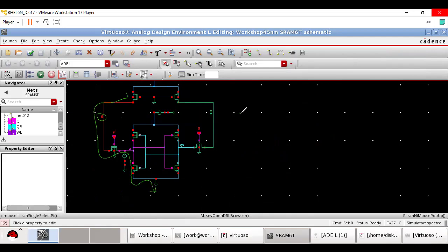If it is coming down from 700 millivolts to only 300 millivolts, it means the whole potential is not being grounded. There is some resistance. Now, what is the resistance? Resistance can be some MOSFET. Either this MOSFET is resistance or this MOSFET is resistance.